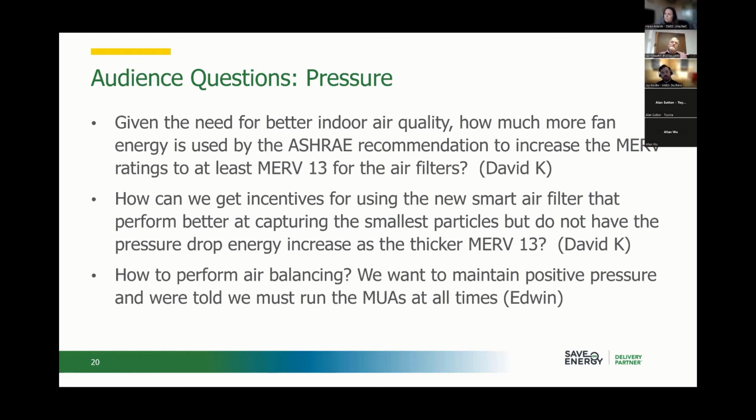When air balancing is being performed, somebody's going through and doing their adjustment at all the different points in the system to make sure that the correct amount of flow, or the design flow that they were looking for, is met at each one of the individual locations. That implies that they're measuring flow. If you look at any air balance report, they measure all the different flows, and they may be doing a total flow, and hopefully the different sub ones match the total flow.